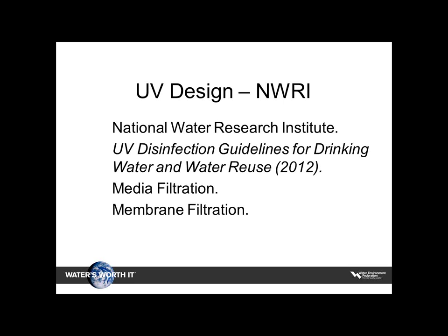So we're looking at, do you have media filtration, a rapid sand filter, a mixed media filter? Do you go to membrane filtration? And the last one, of course, would be reverse osmosis. So there are different levels, with different requirements for each type of filtration. Again, that's really going to be a function of the suspended solids, the material that's carried in there.